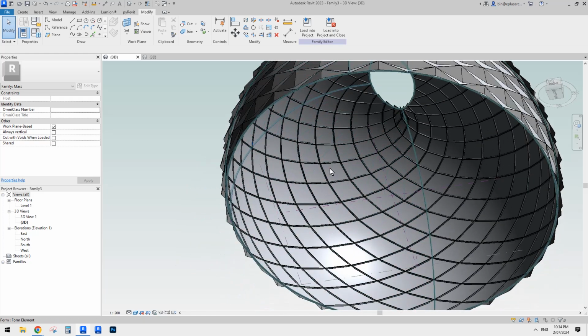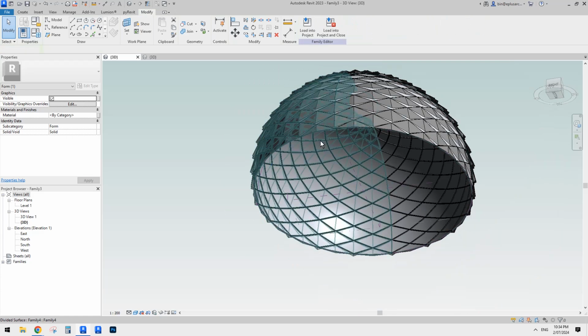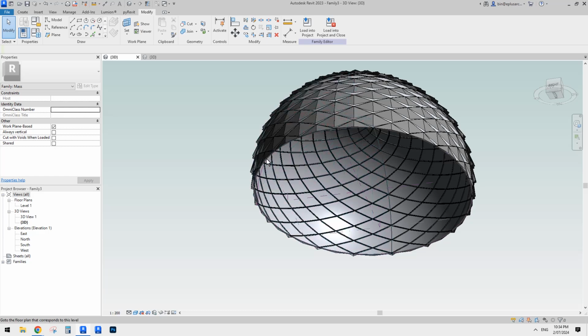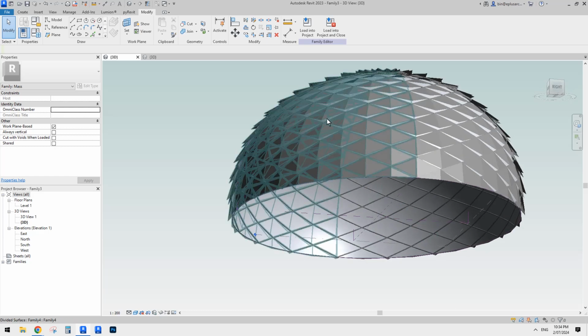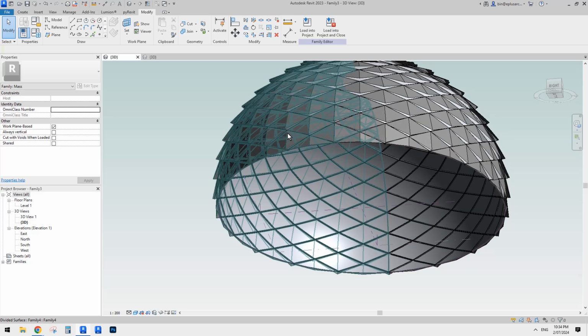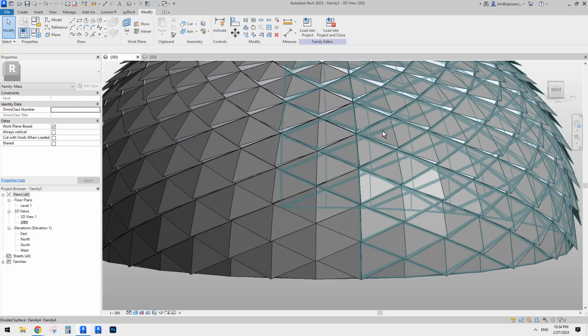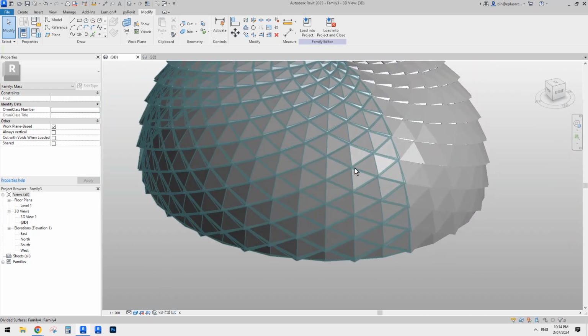And so currently we still have another surface behind, because when we create the form, we use a closed loop, so it will create two surfaces or a solid. And then we only change the surface one into a divided surface, and there's still another surface in the back, so you can see that it's not look through. So that's okay.